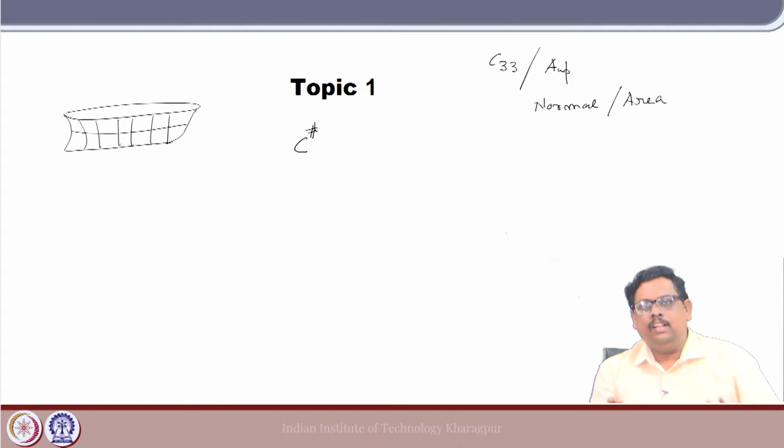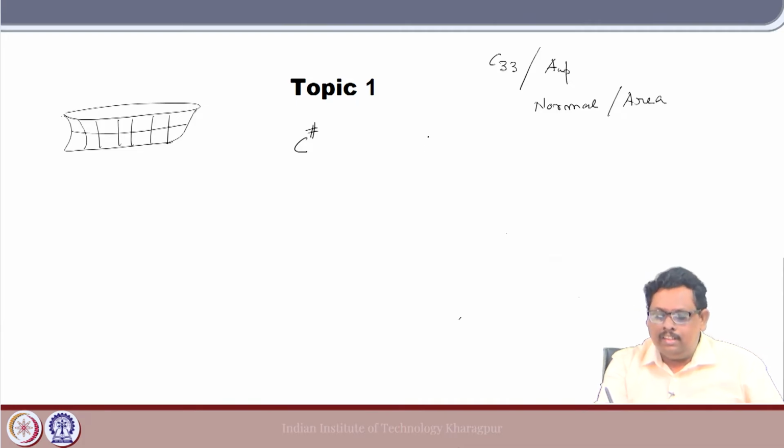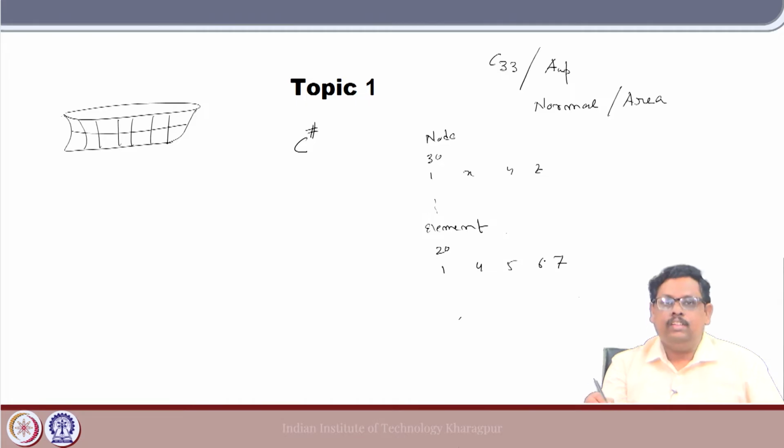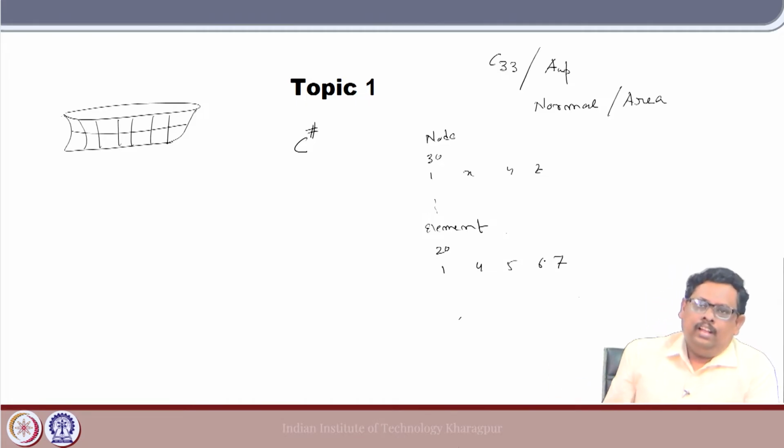If you remember, we write the nodes first, then the total node number, then node 1 with its x y z values, and after that we write the elements. Let us take element 2, and with that I write the connectivity 4 5. In that way we know how to systematically do the meshing.